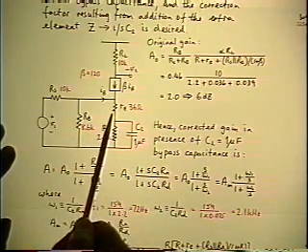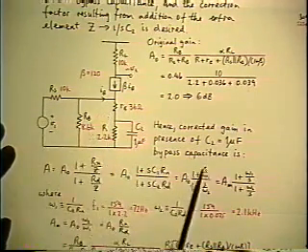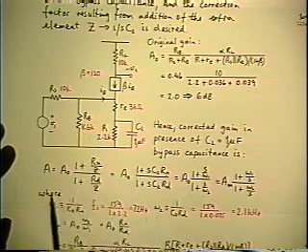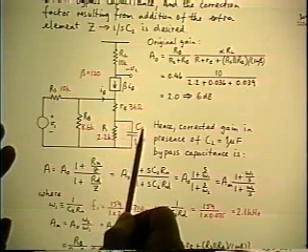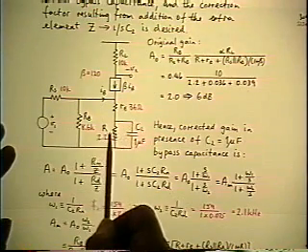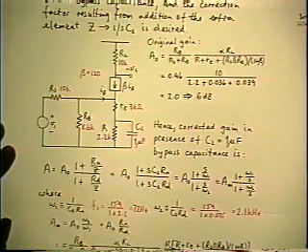It's the pole. And so it's a common error to guess that the bottom end of the frequency response is determined by the C2R time constant. It isn't. It's the wrong corner.